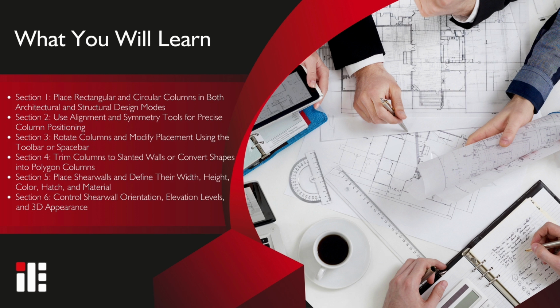In this video, you'll learn how to create and customize columns and shear walls in ideCAD Architectural for accurate structural modeling. We'll show you how to place rectangular and circular columns in both architectural and structural design modes, adjust size, elevation, alignment, and material properties, and use symmetry tools for precise positioning. You'll also learn how to trim columns to fit slanted walls and create polygon columns for irregular shapes.